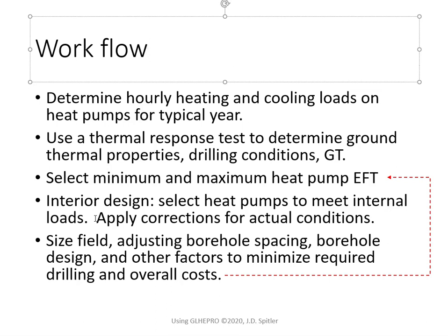Let's see, we've done that in our example on the modeling of heat pumps, right? In that case, the standard return air condition to the heat pump was, I think, 80 degrees Fahrenheit, which is a bit high for typical North American practice, at least if you're not mixing in outdoor air with it. But in any case, you'll choose some heat pumps, and then once you've done that, you can size the field. You can adjust the borehole spacing, the design of the borehole, and other factors to minimize the required drilling and overall costs.